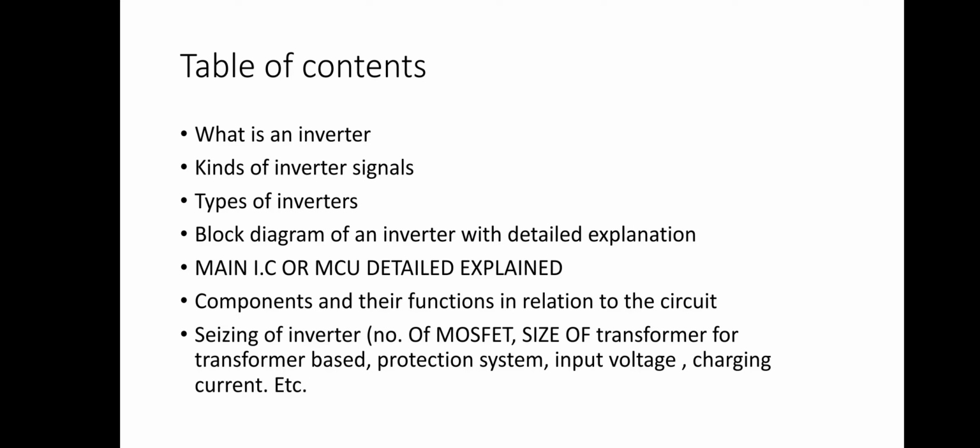Then the input voltage. When designing an inverter, what will determine your input voltage will then determine the capacity of the inverter, and vice versa. Let's take an example of a 1 kVA inverter, which is mostly a 12 volt system. If you are going for 2 kVA, we recommend a 24 volt system, so that it will lessen the work in the transformer-based system. But if it is transformerless, it works with very high frequency systems, so some of them don't literally need to go by such voltage at a wide range of wattage.